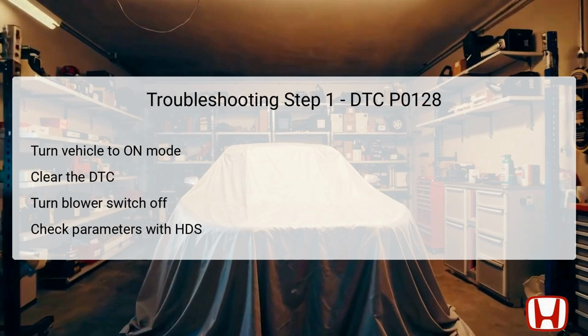The first troubleshooting step for DTC P0128 requires setting the vehicle to on mode without starting the engine. This allows the onboard diagnostic systems to become operational and ready for assessment. Following this, it's crucial to clear any existing diagnostic trouble code using the Honda Diagnostic System, HDS, which is a specialized tool that facilitates communication with the vehicle's onboard computer.